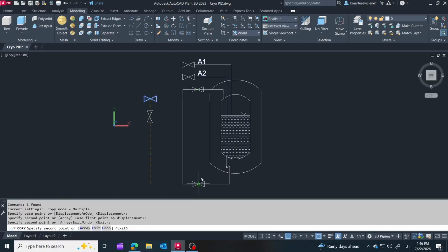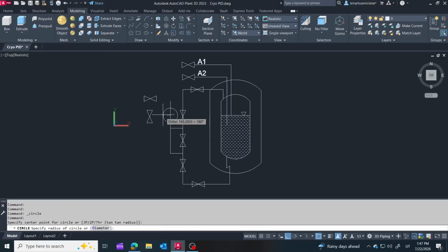These two nozzles are primarily used for differential pressure level measurement. The upper nozzle senses the gas pressure above the liquid, while the lower nozzle senses the pressure at the bottom of the tank. The difference between these two pressures is proportional to the liquid height, allowing the level inside the tank to be calculated continuously. Since both connections experience the same tank pressure, the differential pressure transmitter effectively measures only the hydrostatic pressure created by the liquid column.